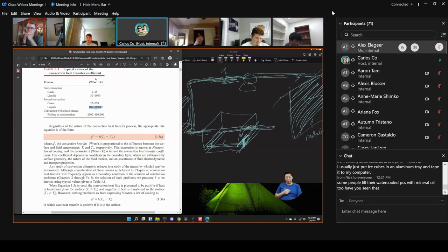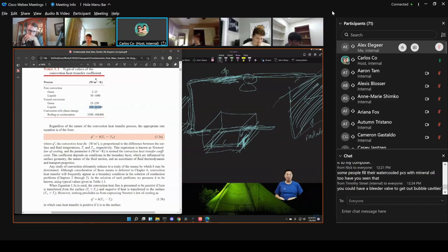Then, of course, the efficiency of the cooling degrades. But way before that happens, you're going to have air bubbles in there, and when the air bubbles pass through the pump, you get something called cavitation, which is extremely noisy. It's so annoying, right? So some people might change the liquid coolant to something with less volatility, or something less permeable through the hoses. Some people use mineral oil or things like that. With me, I just usually swap out my water cooler as time passes. It's a pain to replace those, but they're not expensive.